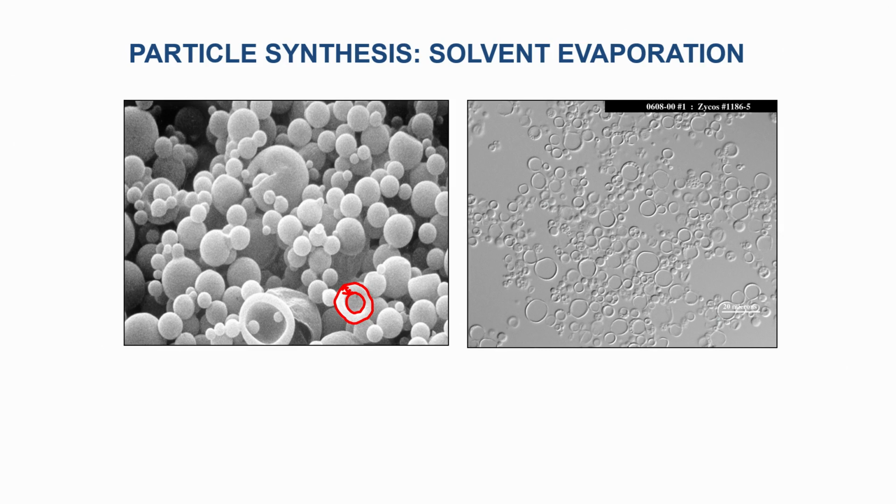So, this is an SEM image. You can use other techniques, you can determine the particle size by dynamic light scattering, using a Coulter counter or other similar instruments, and you can get some sort of an idea as to what the size is. In this case, since this scale bar is about 20 microns, we can say that the average size here might be about 5 microns, but you can then again vary that by changing the energy that you are providing to the system.